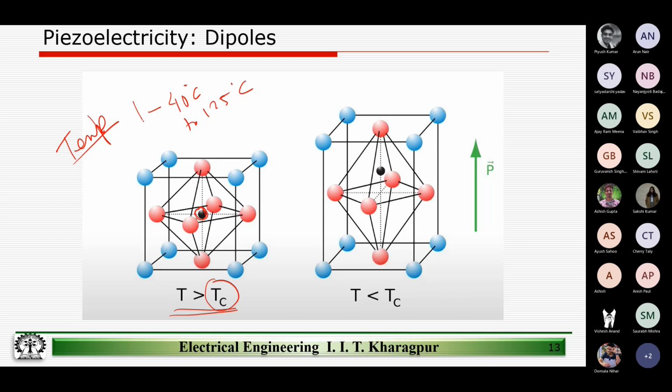So this is the typical range of temperature for consumer products. For military, it is a little bit more, or for automotive also it is a little bit more. So for that we call it extended temperature range. That becomes from minus 50 to 150. But the electronics or the transducers that we design, typically we want to make them work from minus 40 to 125